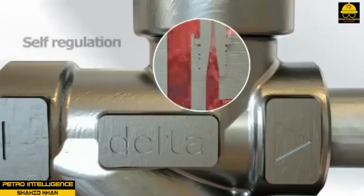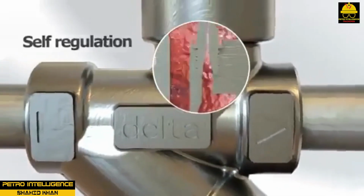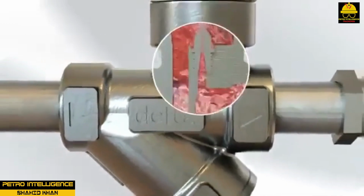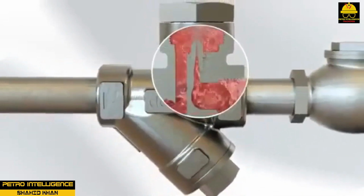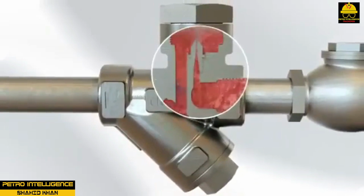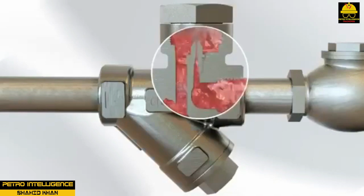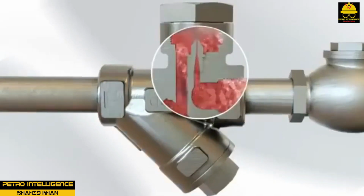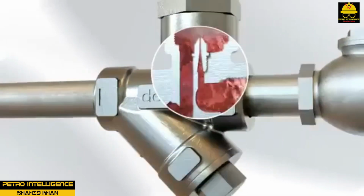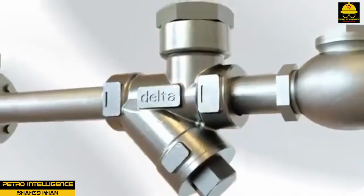Steam traps are sometimes considered a special type of check valve. They permit flow in one direction only. In addition, they permit the flow of only certain fluids. The basic purpose of a steam trap is to allow hot water or steam condensate to pass while holding back steam. Steam traps are sometimes used on steam-heated process equipment to remove large amounts of condensate.